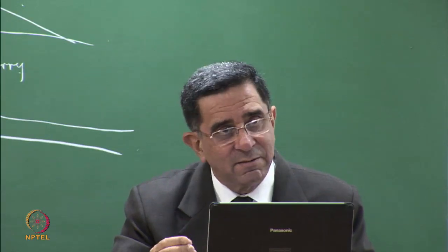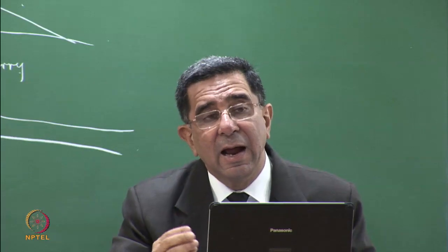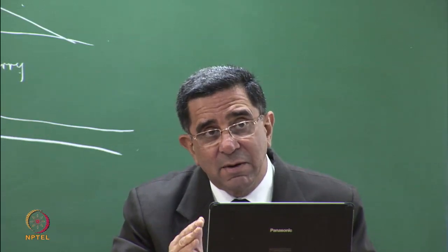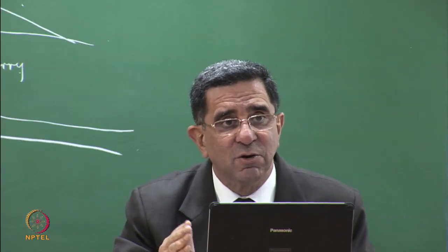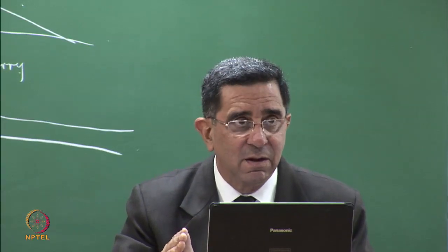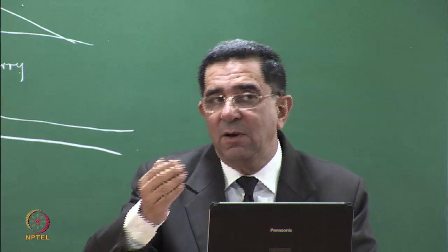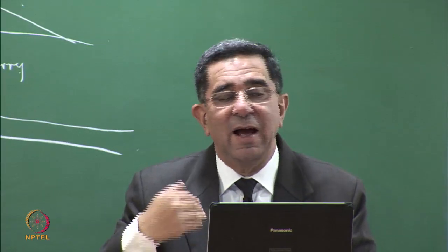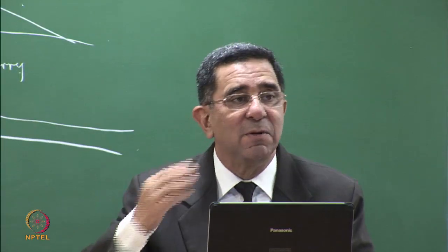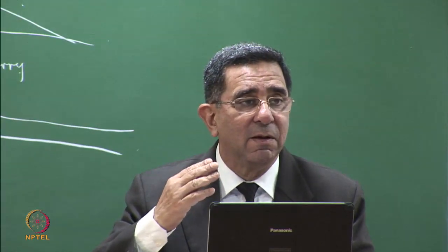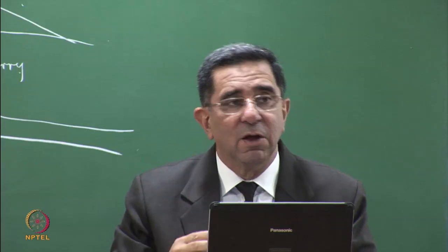You can make a thread, right? And beyond the liquid limit, it is not going to behave like a solid medium. It is going to behave like a thick slurry. So, depending on your liquid limit, you can have 40% moisture content, 50% moisture content, and then it begins to behave like a thick slurry.